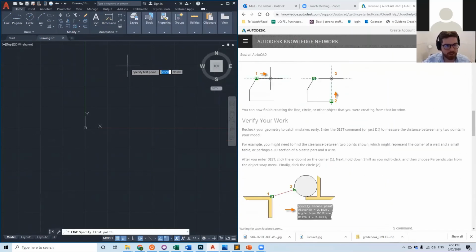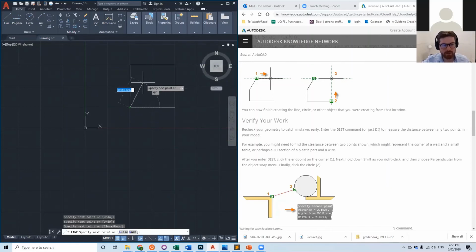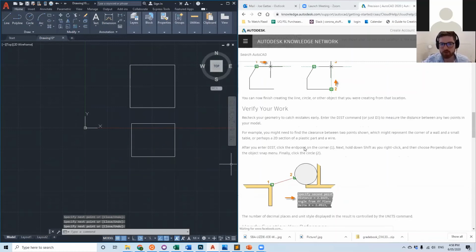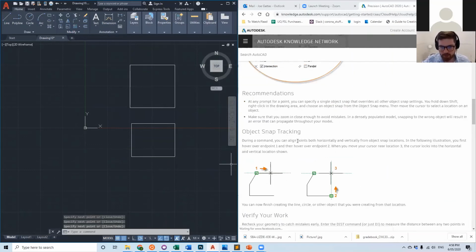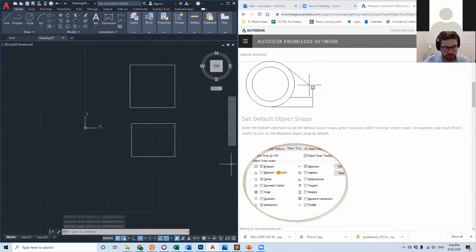There's one other point here that you might have seen just as my cursor jumped around. As well as the snaps, it'll have these guidelines. So it will try to help you match things up. It's trying to keep it horizontal with this line and then vertical with this line. So this is a parallel rectangle. Using the guides is much easier than trying to just guess this in space, because if I try to guess where the end of this point over here is, it won't work. If I try to match the guides up, it works really well. So use your guides, or they call it snap tracking. Use your O snaps, use your grid snaps while you're getting up and running.